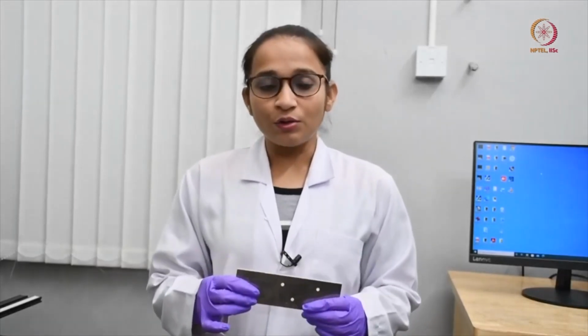So we are going to take this specimen and use emery paper to abrade it. This emery paper is going to create random patterns on the surface of the specimen, and we have to decide the grit of the emery paper based on what scale of resolution we require in our results.